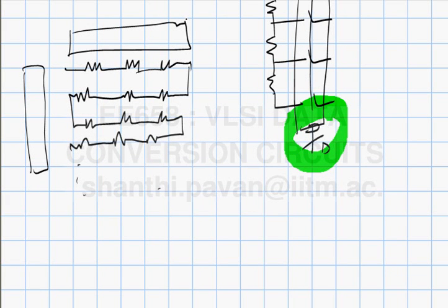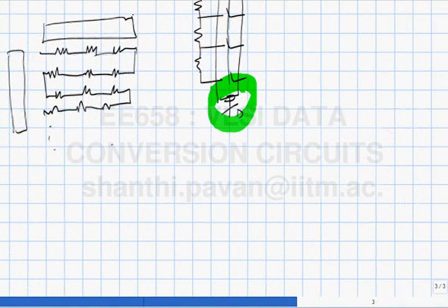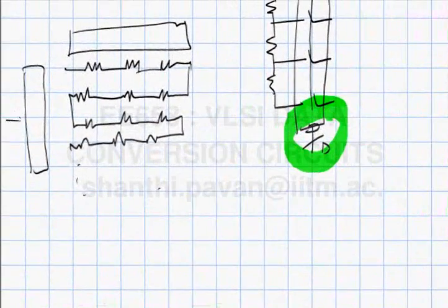And this is very similar to what you do with accessing memory in a RAM, right? So you have a row decoder and a column decoder, so half the bits will come here, the other half of the bits will come here, and the decoder complexity is reduced quite a bit when compared to having a dumb decoder which takes the 8-bit word and generates everything.